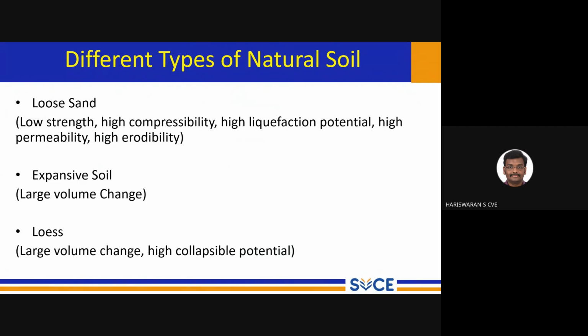After drying, it may undergo shrinkage. So these two extreme conditions directly affect the foundation element. Ultimately, the whole superstructure may face a problem because of the nature of the expansive soil. In Chennai, most of the area has expansive soil at the top layers, then loose sand, right?